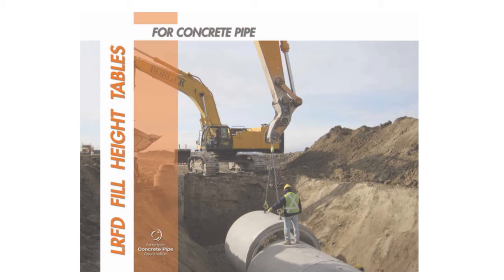ACPA LRFD bridge design under Section 12 allows for direct or indirect design of concrete pipe. Direct design is a very calculation-heavy method to determine the reinforcing and concrete requirements in concrete pipe. Indirect design allows you to determine the load-carrying capacity of a pipe by utilizing a simplified relationship between the installed condition and a test condition in the plant.